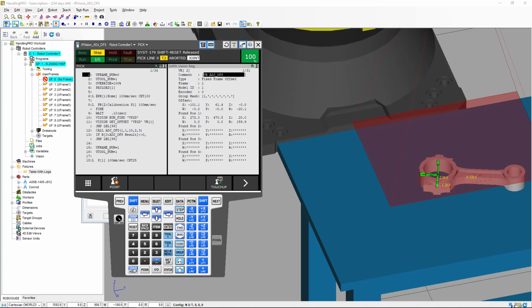I showed you that there is a way to fix this offset problem using the KAREL program, adjust offset, but this is only a band-aid that can help you temporarily, and you really need to address the root cause of the problem. Also, be aware that if you want to use this KAREL program, you need to have the option package Vision Support Tools installed.